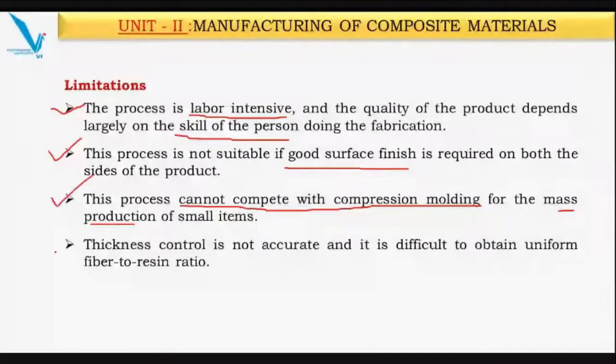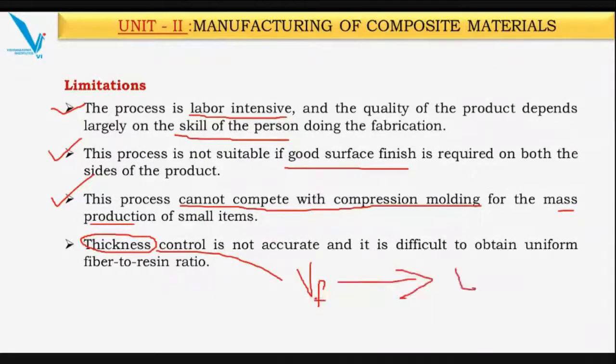The thickness control is another issue, because thickness directly relates to the volume fraction of fiber, and the volume fraction of fiber is directly related to the Young's modulus and the strength. So thickness control is very difficult here. Maybe you can use some spacers, but there you need to compress. If you are using the mold from one side, you don't have any control over the thickness. So that is another challenge. Thickness decides the volume fraction, which decides the strength, so for structural applications, this method cannot be used indirectly. That's what we can conclude from this.